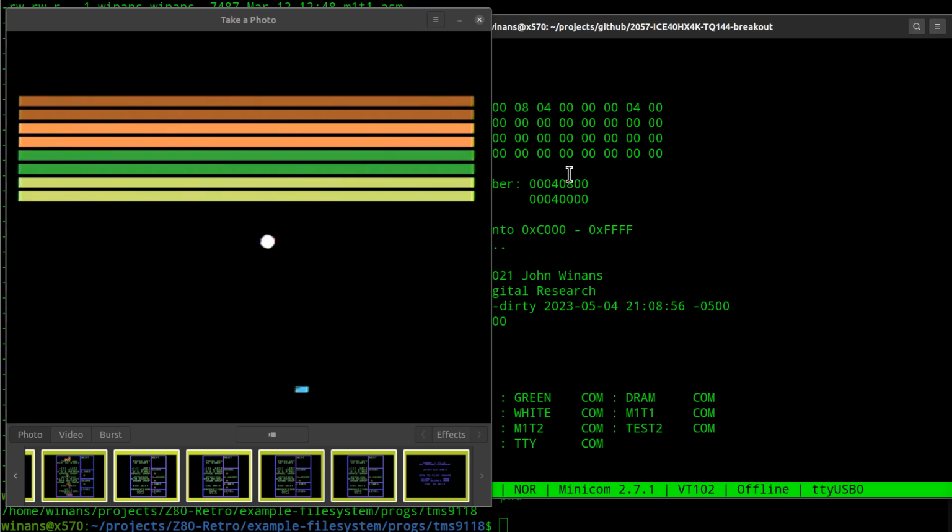Now, this is with the 27 pF capacitors. This is an infinite amount better than it was with the 43s, which didn't work right at all when we pulled the frame flag. While the 47s were in there, I also ran this version of Breakout, and it also behaved just fine and dandy.